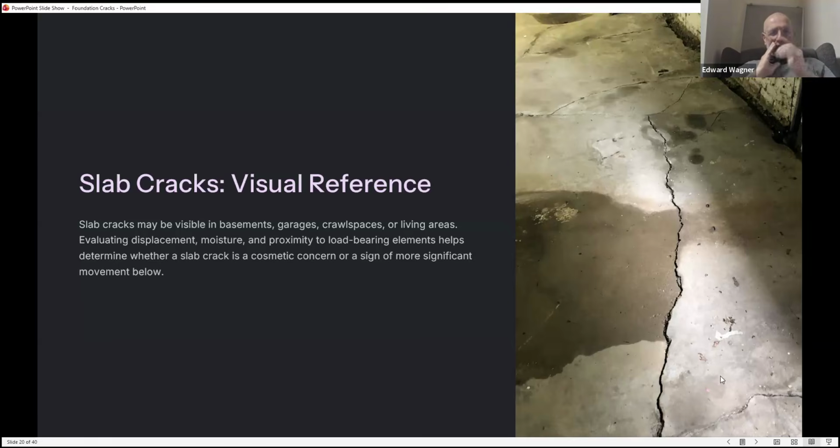Stan, can I add something to that? Sure. What I see in basements and garages is they put an overlay on to hide the cracks. They'll put 2 to 3 inches of concrete on there, and it's crazy when you see it. You can tell in the basement because the bottom stair stringer, the first step, is now much lower, buried, than it was originally. Or in an old garage, the floor looks perfect, like there are no tire tracks or anything. I know that's a bad thing to do. I'm just saying I've seen it. That's one of the ways they've tried to put a Band-Aid on things.